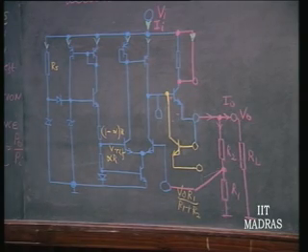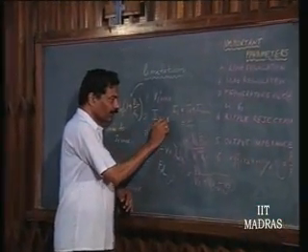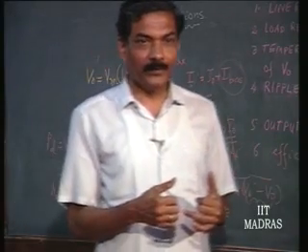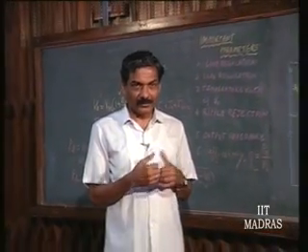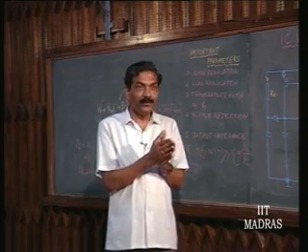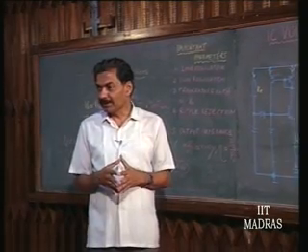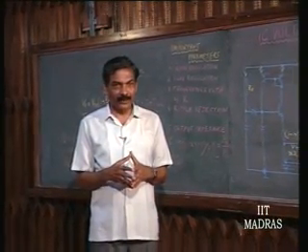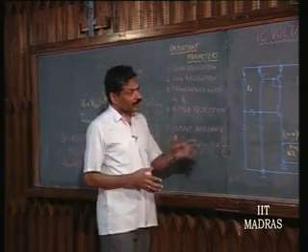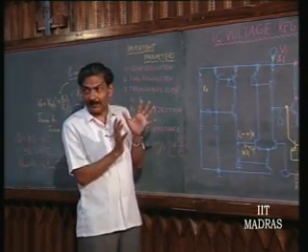So, I naught has a limitation on this, that I naught max is something that can come about from P D max also. If it is not given, and you know the variation of V I from V I minimum to V I max, then you can get a limitation on I naught max from the circuit. That is based on power dissipation. Now, there are a variety of things here. You should understand this circuit thoroughly when you are a designer.